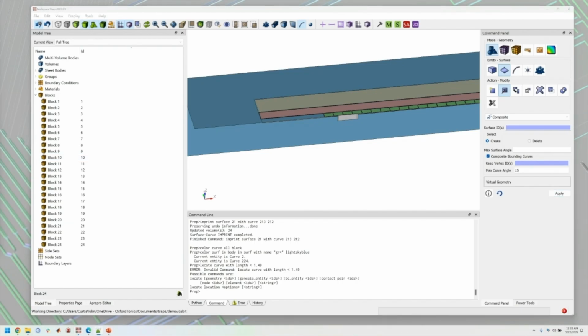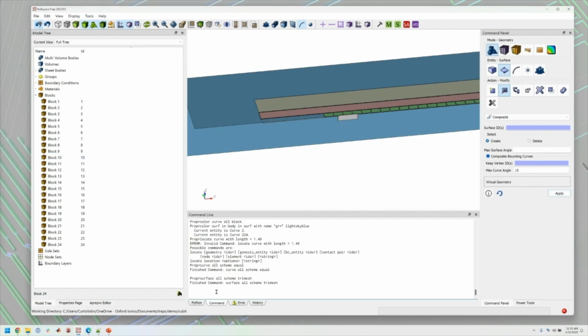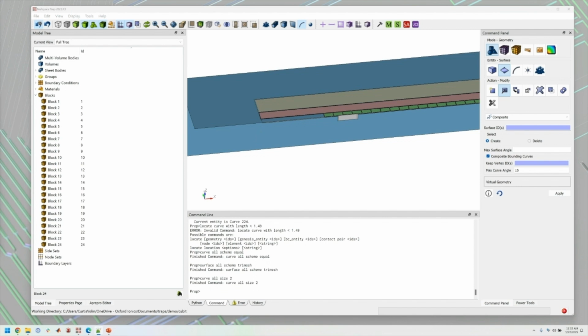So now we can go back to meshing again. This is one of the most powerful things of this software, and the main reason you want to use it is that it generates this adaptive mesh. I think that's probably not the right word, but it makes triangles that grow as you move away from the edge, and that's very well aligned to the physical reality of what we're trying to simulate. All we have to do is tell it to make triangles, and then define the curve size on the edges and let it fill in the rest with a single line command.